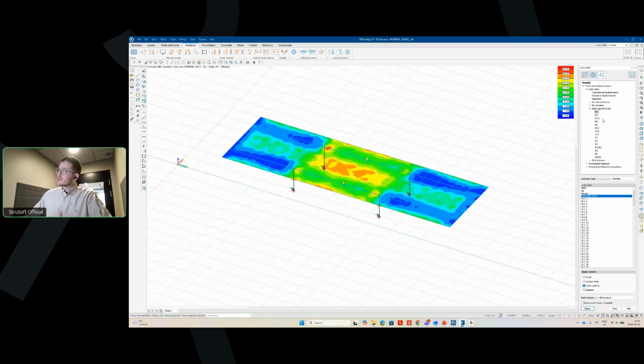One thing to note is that even though you can find these traffic loads in the load cases tab, the results for these are envelope results. So there are really many results in each of these cases. So you select your result and you go to load, generate load cases by patterns.